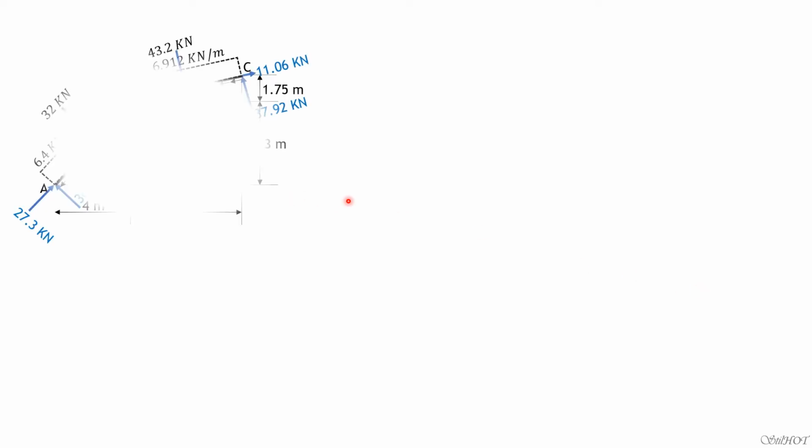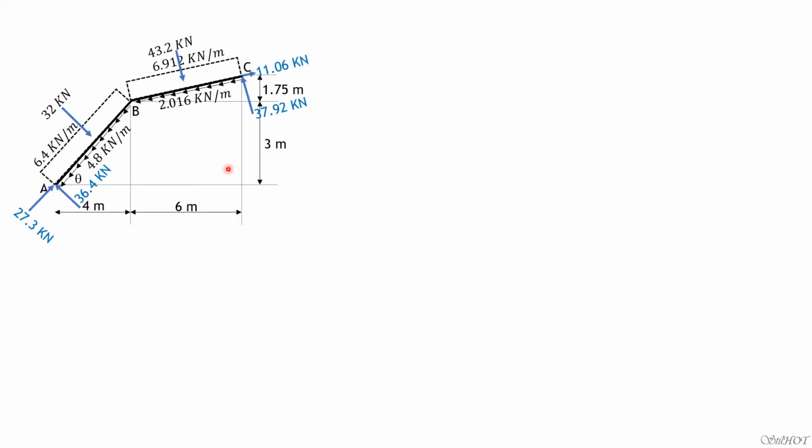And here, at the last part, let's now construct the shear and moment diagram. So for the shear diagram, first we rise by 36.4. So shear diagram in kilonewtons, 36.4 minus 6.4 times 5, or minus 32, is positive 4.4.